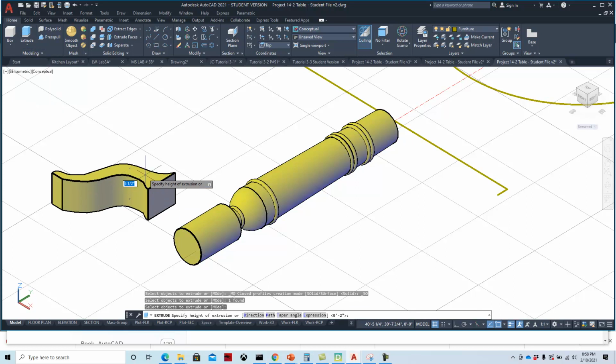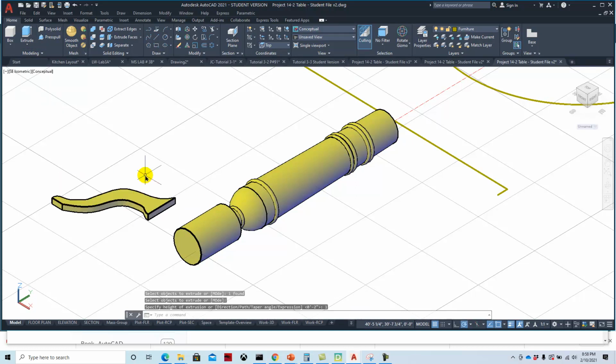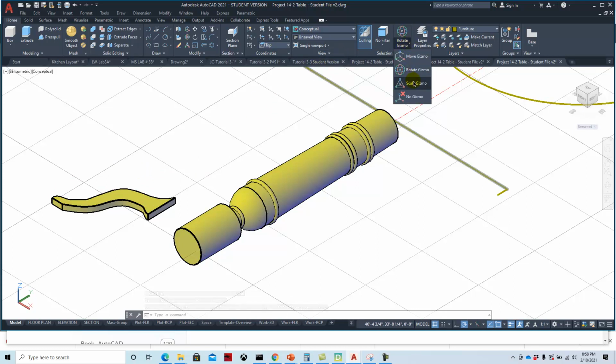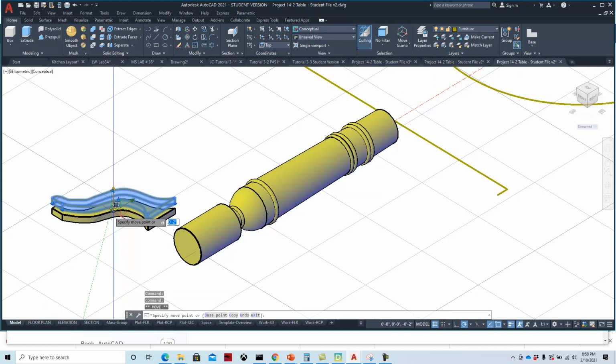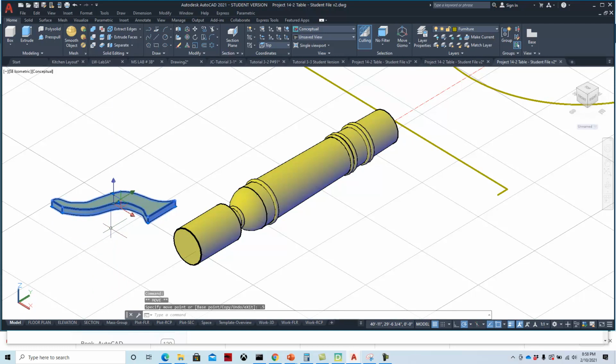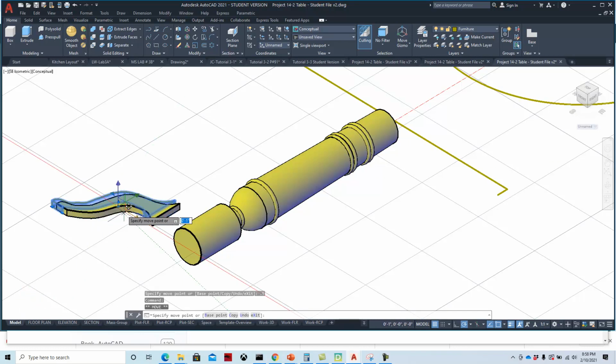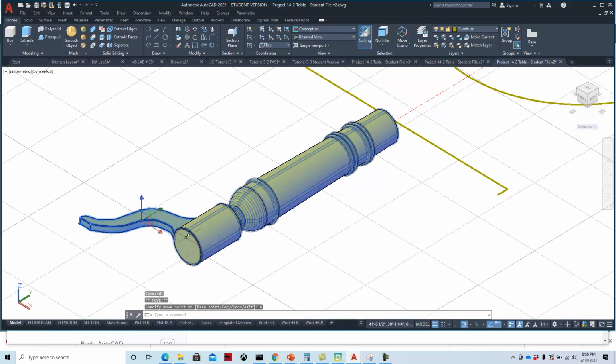And we'll extrude that 1 inch. And then what we'll do is we'll move it in the z-axis. I'm going to just kind of over push this down, and I'm going to say 0.5. That way, when we move this over by grabbing this rocket, or the x-axis, 6 inches, it will be centered on the column.